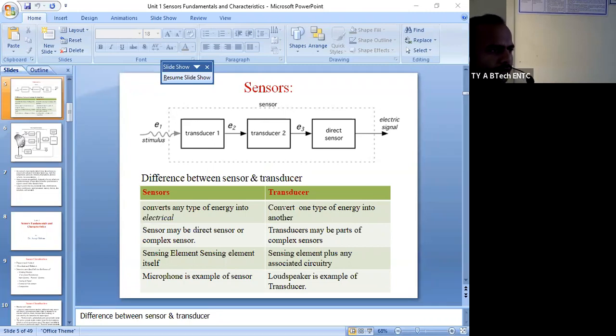For that purpose, you have to go for any kind of ultrasonic sensor. If you guys are familiar with the ultrasonic sensor, if you put it on the top side or roof of the tank, it will continuously measure or monitor the level, the empty space, and accordingly you have to calculate. This is the feedback mechanism used with the help of the output of an ultrasonic sensor, which is provided to the microcontroller or computer based system. Here computer is mentioned, so either from a computer or from an embedded microcontroller system you are able to track or control this.